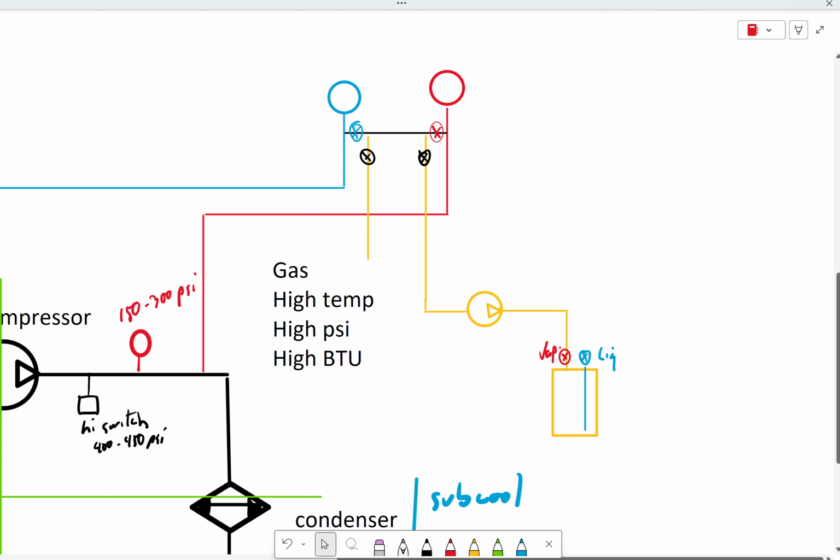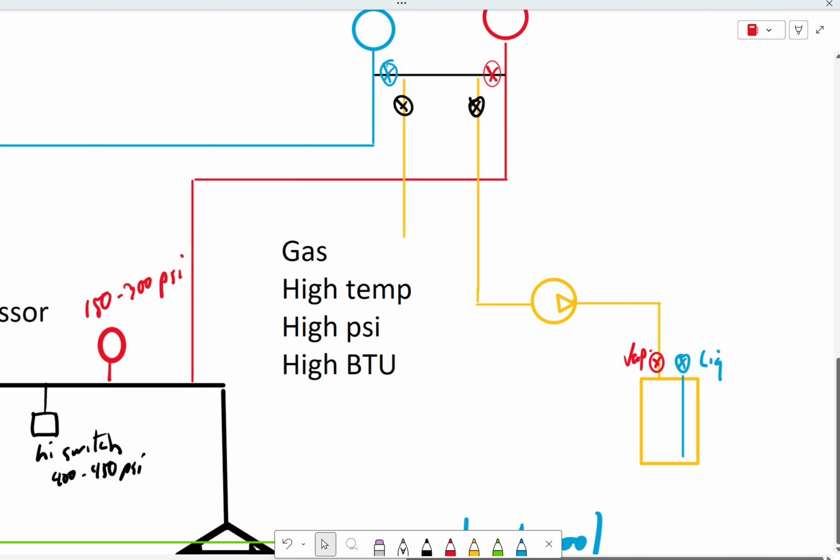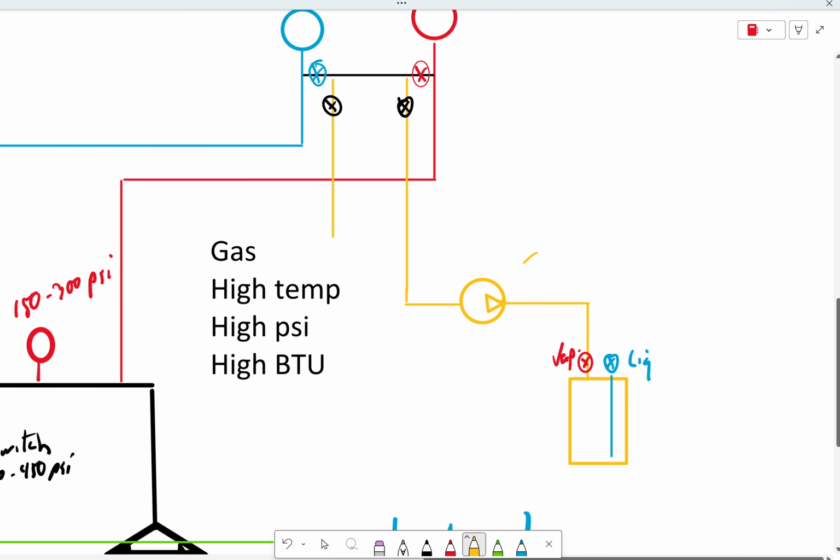So what I'm going to do is recover the refrigerant. I'm going to pump it out of the system into the bottle. That bottle's sitting on a scale, because I'm measuring how much I'm taking out of the system, and I measure that in pounds or kilograms or grams or pounds and ounces or whatever you want. I'm measuring the mass of how much I take out of the system. You'll notice right now, I don't actually have that extra hose on my 4-hose gauge set hooked to anything, right? So right now, I'm recovering. That means that this right here is a recovery unit.